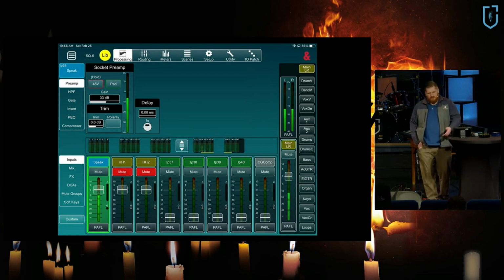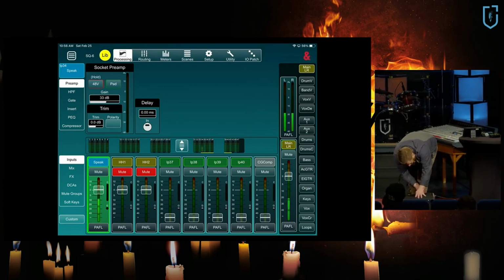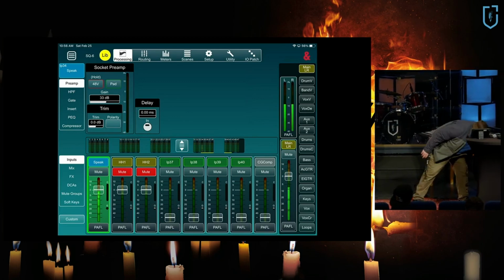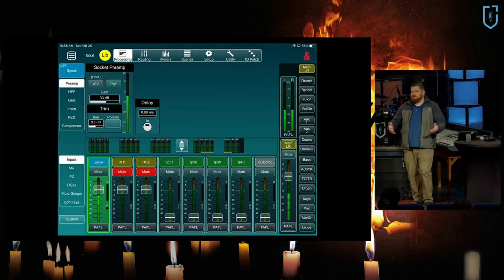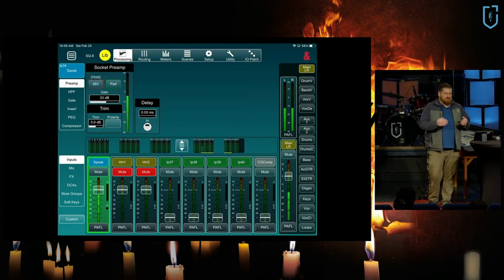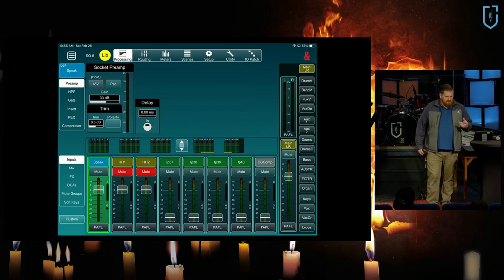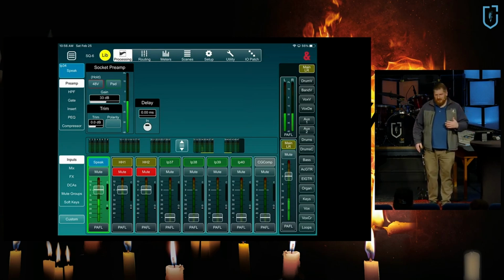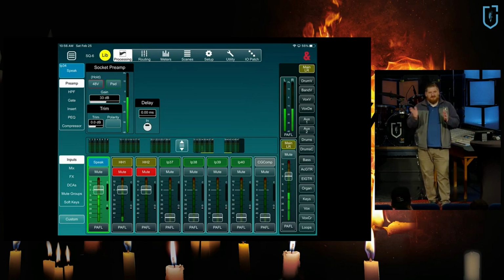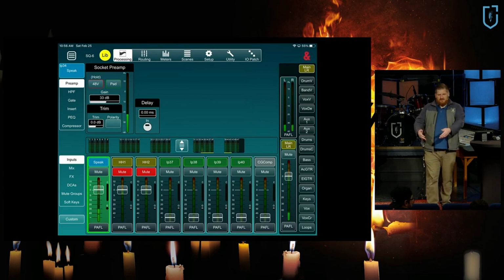The problem you run into is that a lot of places, front of house does more than front of house. You're mixing monitors and you're mixing your live stream. When you do that, all you're doing is mixing directly for front of house. If it comes out of the speakers at the right volume, it's fine. But you're cutting your signal strength, and that's the signal that's sent to those auxes. So now you don't have enough to send to your monitor.